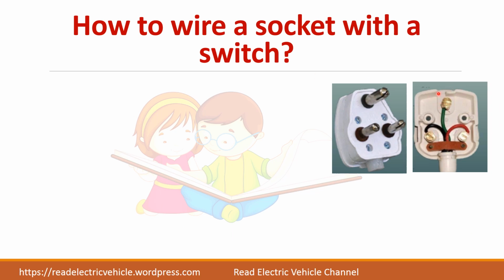The upper one is the earth pin, green color is used, and here red color for the phase and black color for the neutral they have used. Always remember the color coding or check the color coding for your country. Now this is the older version. In the new version they have brown and blue.